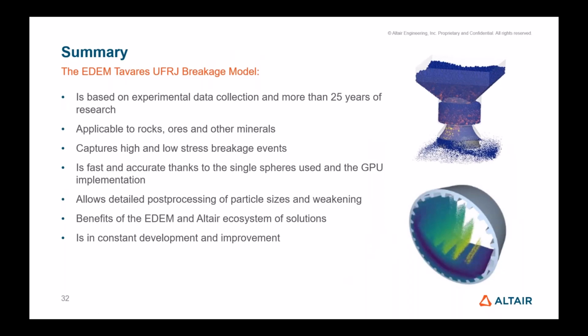Okay, so that brings me to the end. So with the summary slide of the topic we've presented today, which is the EDEM Tavares UFRJ Breakage Model. So to recap, it is based on experimental data collected over more than 25 years of research by the group of Professor Tavares. And in general, it is applicable to rocks, ores, and other minerals, even though, as I said before, it can also be used in other areas, in other types of materials, but might need more work in terms of setup. And the model can capture both high and low stress breakage events, surface damage, catastrophic breakage. And it is fast and accurate thanks to the single spheres methodology used and the GPU implementation in EDEM. And a key thing of that is that you can post-process very fine particles without actually the need of simulating all of them. So we save simulation time, but we don't save accuracy of results.